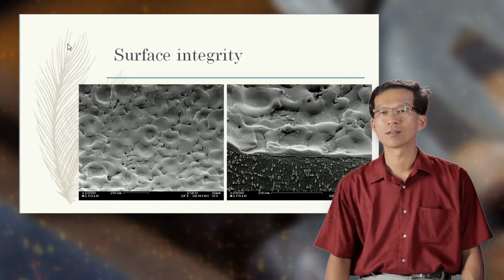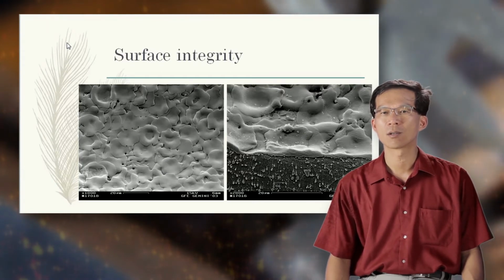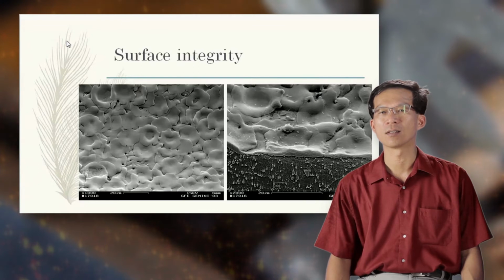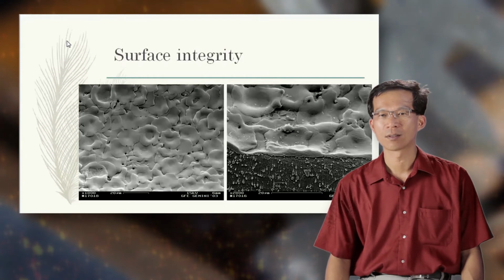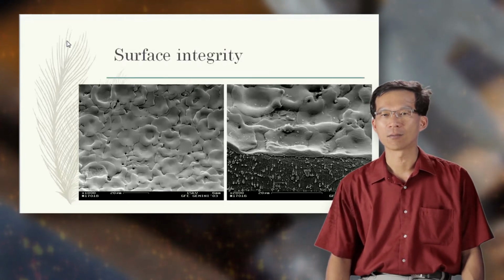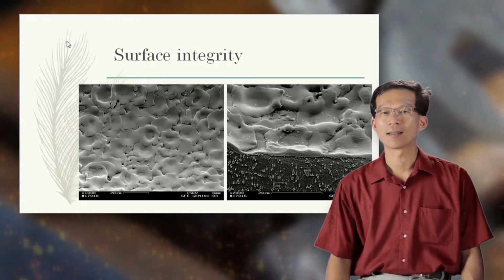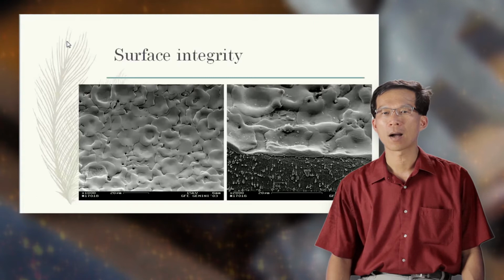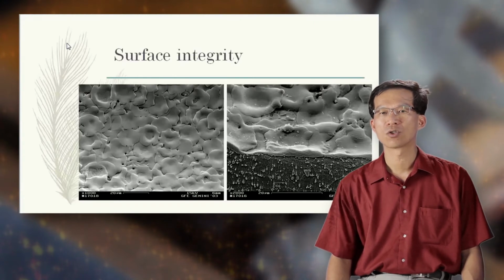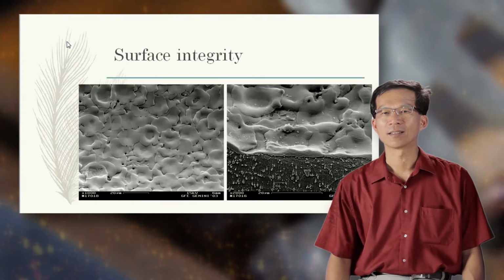These photos reveal the distinctive morphology of a surface which has undergone micro-EDM machining. An enormous amount of heat is generated by the discharges. Melting and vaporization of the material occur and are followed by rapid cooling. The surface profile reveals that the surface roughness is caused by uneven fusing structures, shallow craters, pockmarks, voids, and cracks. The microstructure of this layer is quite different from the parent material.